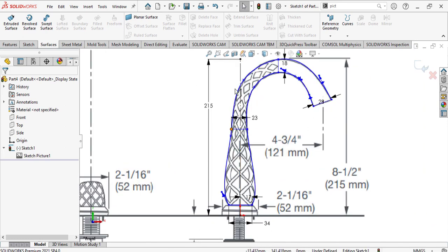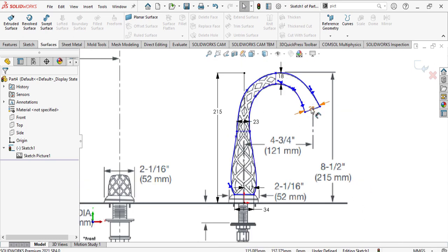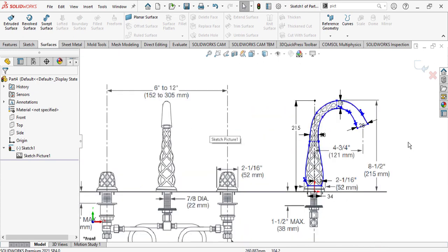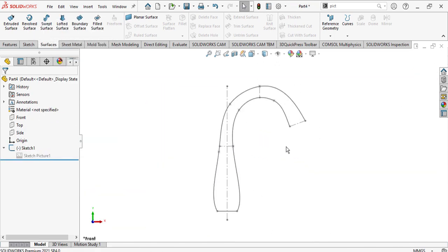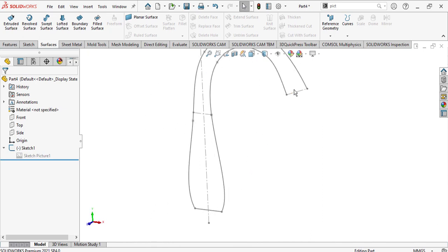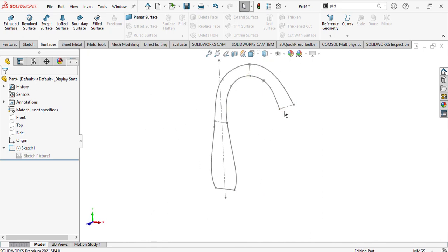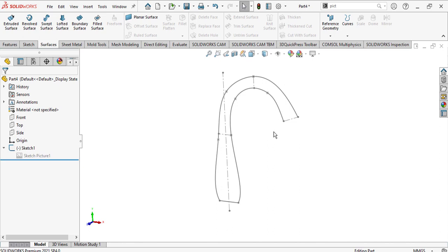Now we have made a guide curve and some lines as guides for our profiles. I need to build my profiles here. I assume my profile here and at these lines is circular, so out of here I can suppress this and add your circular profile here. I need to make this by adding the first plane. I need to make a plane here.